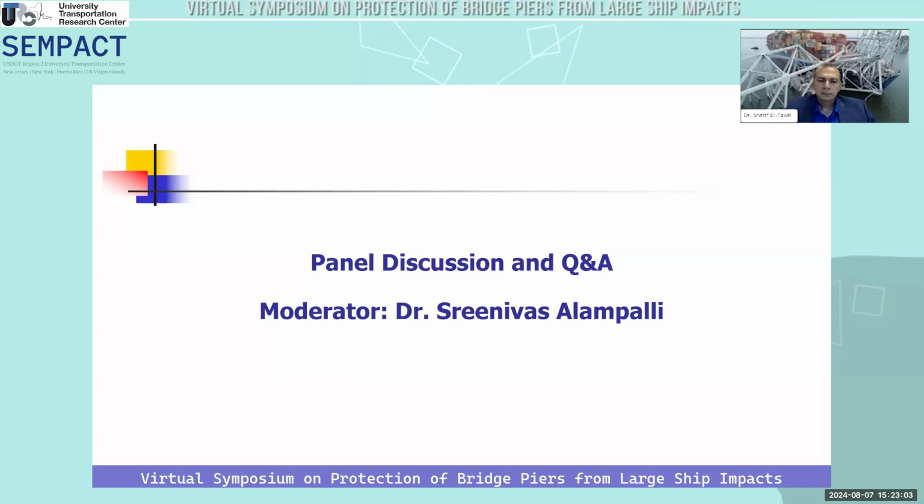When we look at any sort of impact event, and the one I'm most familiar with is cable loss, anytime we do these as equivalent static loads, we get very different results. In our practice, we do everything associated with an impact dynamically. Even on a large scale structure, the equivalent static loads just don't represent behavior. And I thought Gary did a nice job of describing the inertial response of the structure and how that matters in the overall behavior.